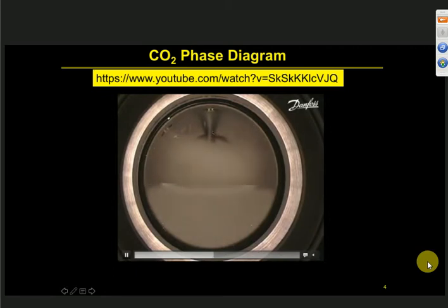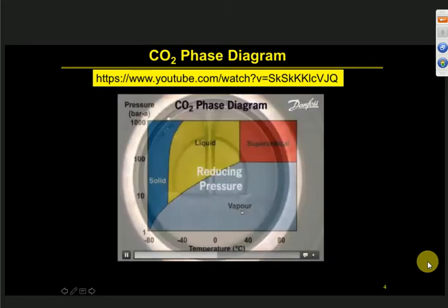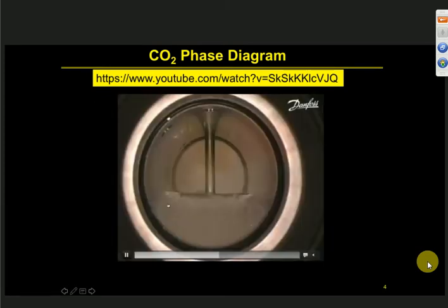As it is going out, it cools down. This is called the Joule-Thomson effect. And then it cools down, and the temperature reaches all the way to the triple point conditions. Then you see the formation of the solid.